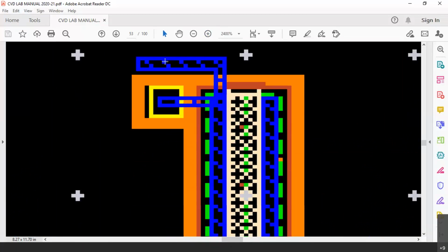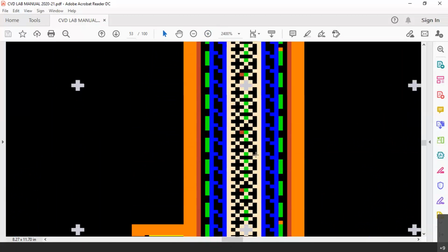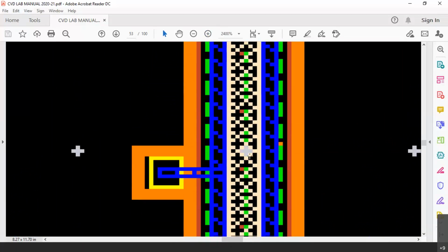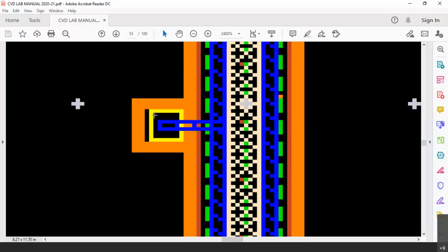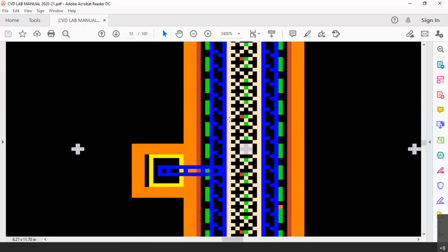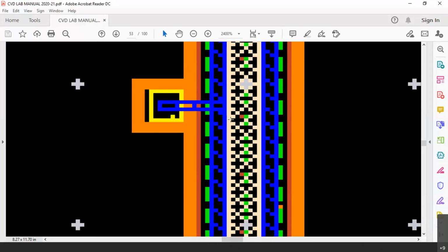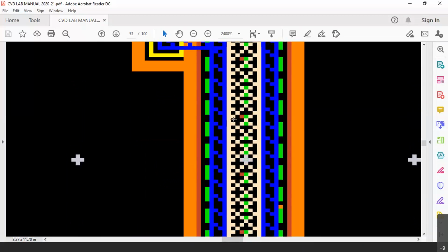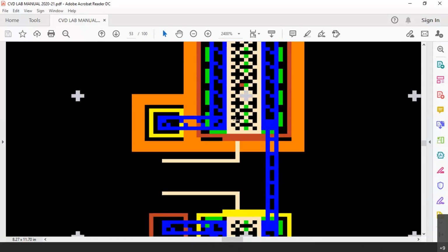Now at the top we have VDD, and the body of the P MOSFET is connected to VDD, and you can see all these metal lines. In between it is polysilicon, the gate area. Every 10 micrometer, there is this VDD connection of the source. See, it is such a lengthy device, such a big device.